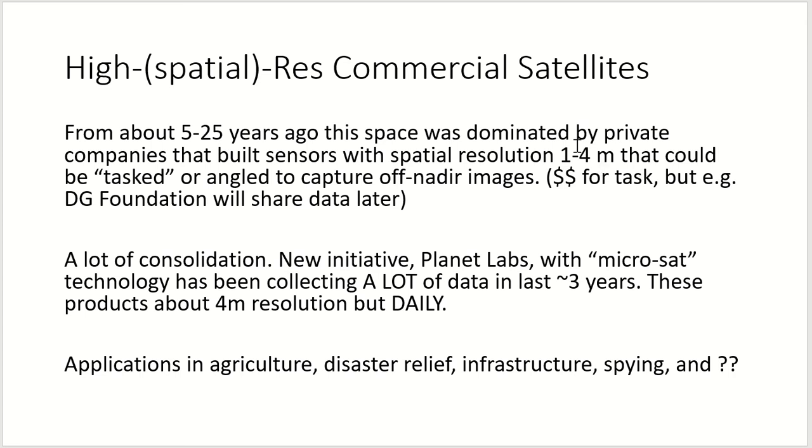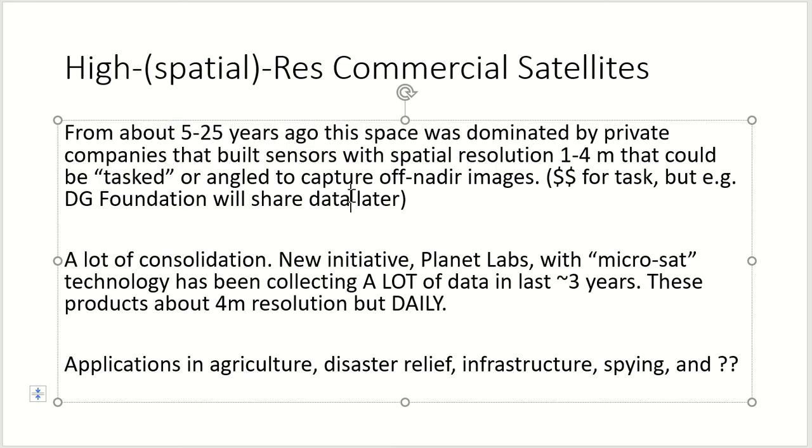And by virtue of their spatial resolution, their orbit, the nadir overpass time, the revisit period would be very long. But these sensors could be angled. So they would be tasked, based on whoever's paying the companies, to capture images of locations that the satellites were not passing directly over. So that's what we mean by off nadir, nadir being immediately below the sensor. So they could be angled to capture off-nadir images.